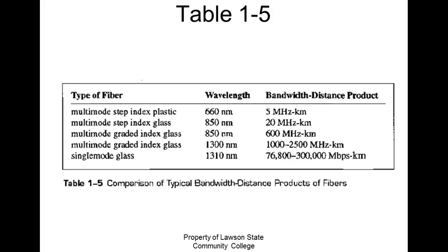So what the megahertz per kilometer tells you, so if I go to 2, then the ratio is going to stay the same. You understand what I'm saying? Yes or no? So that means this has a ratio of 5 to 1. So that means if I double the kilometers, then my speed is going to halve. If I halve the kilometers, so let's say I do it 500 meters, then that means I could run the cable at 10 megahertz. Y'all understand this? That makes sense? Yes or no? Everybody okay? You okay, James?